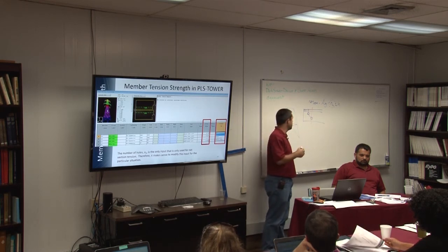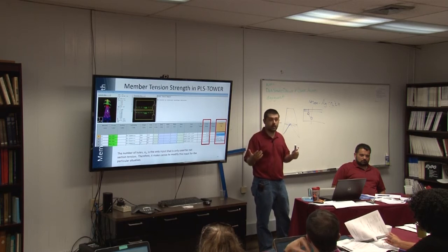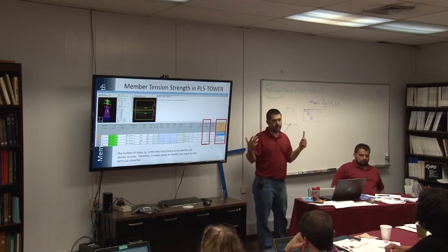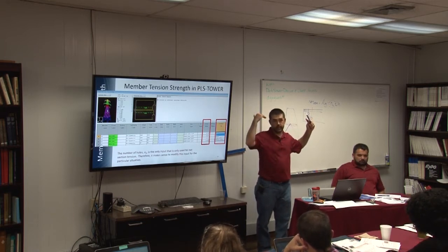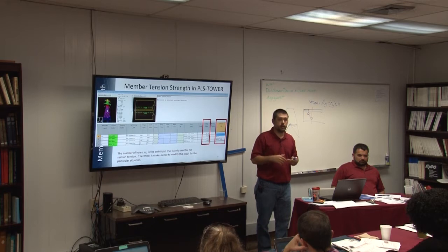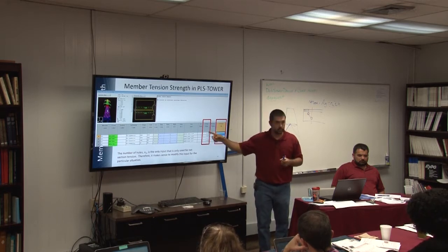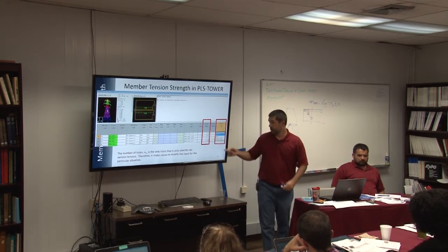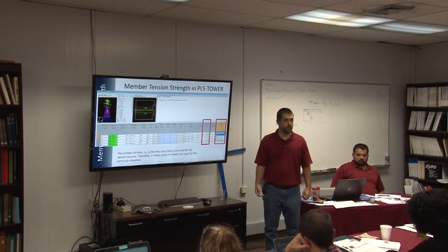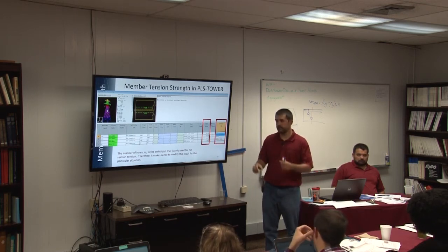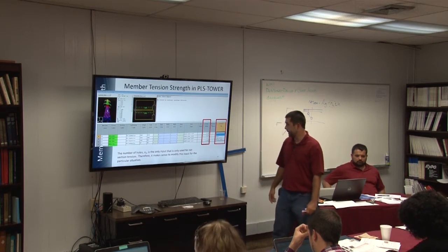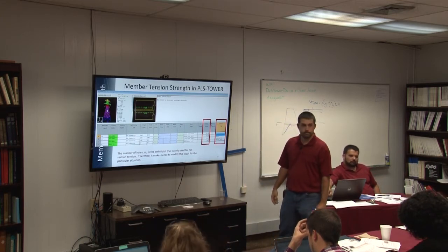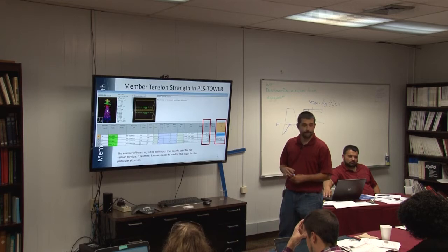So that what it actually calculates as the net area is the calculation you want, whether it's a stagger or the outstanding leg is clipped. You've got to figure out what these numbers are. In almost all towers, these things are going to be non-integer numbers. Only the simplest towers where you have a single row of bolts are these going to be integer numbers most of the time. Okay? So how do you account for the clip? Yeah. Yep.